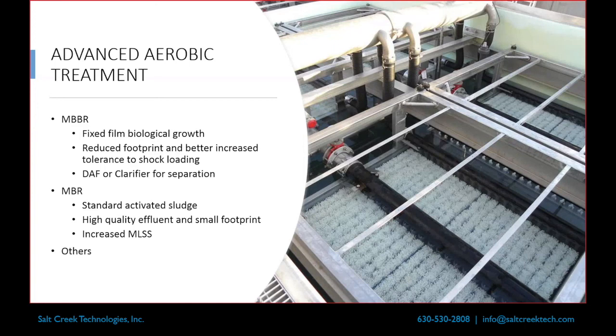And like we said, it does have a smaller footprint. The fixed film biological growth does not have great settling characteristics generally. So that is one area where you do a lot of times see a DAF following an MBBR rather than a clarifier. Not always the case, but in a lot of cases that's the chosen separation device.